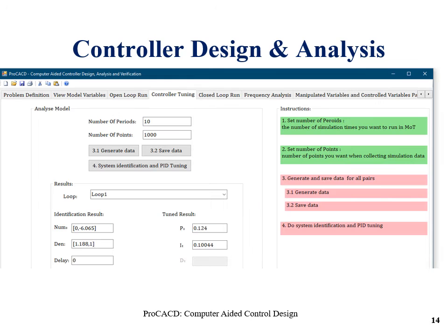Okay, so the next step is the controller tuning. Here you don't need to do the control pairing because we only have one pair, and of course I'll show you what the end result for RGA analysis would be. For one MV and one CV it would be 1, which is like the ideal case.